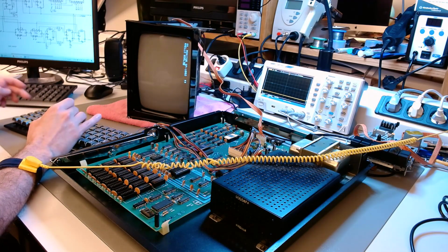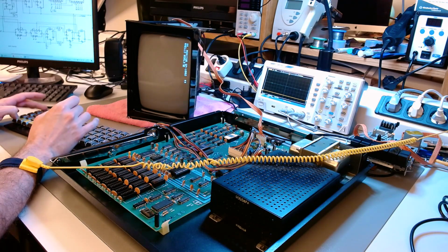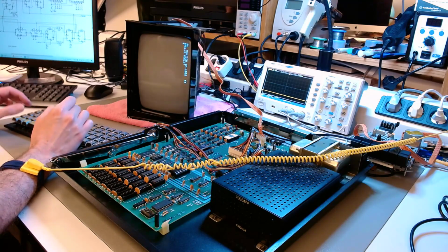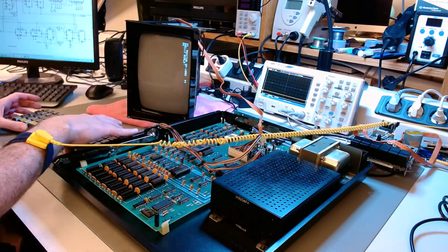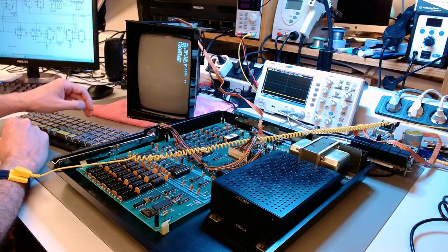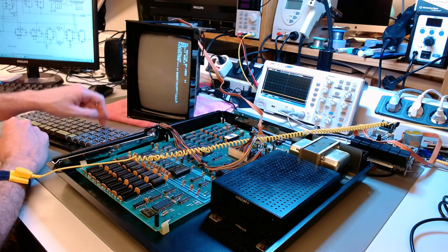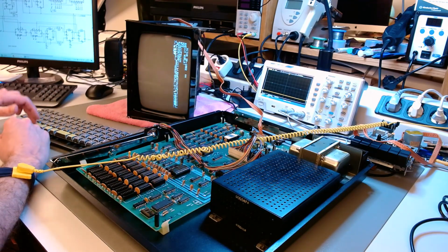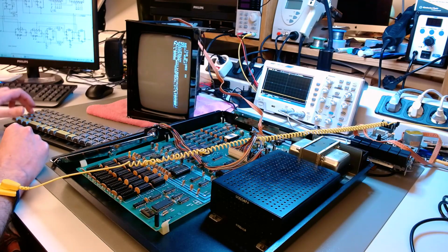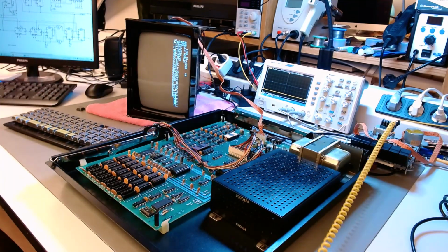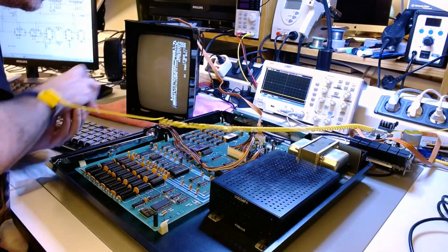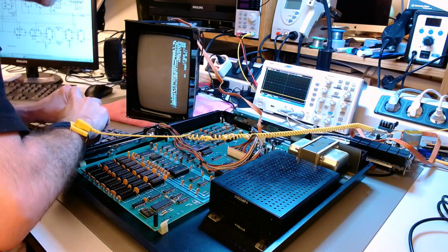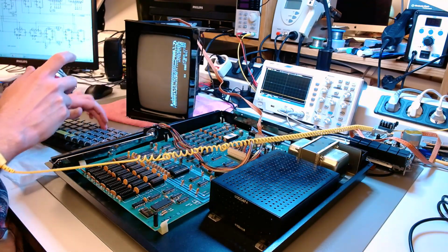Some of them don't react as reliably as I wish them to react. I'm first writing hello world, of course. Then I go through the test of all the keys. The ones that don't react reliably enough, I go back with a little bit more of Deoxit D100, the one without flush action, without solvents. And I sort of squirt a little bit more. That's what you see me do now. Squirt a little bit more, press the keys again. And I did that 2 or 3 times until I was happy with it.